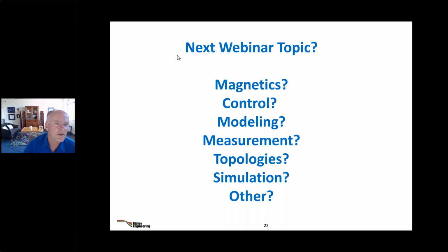Battery charging application, I think it's fine for battery charging, quite honestly. I don't see why you wouldn't do that. You just put a little filter. If you see the pulsing, you put a cap across it. So the cap absorbs the pulses of current, and then the battery doesn't see that. And this happens at low frequency charging as well.